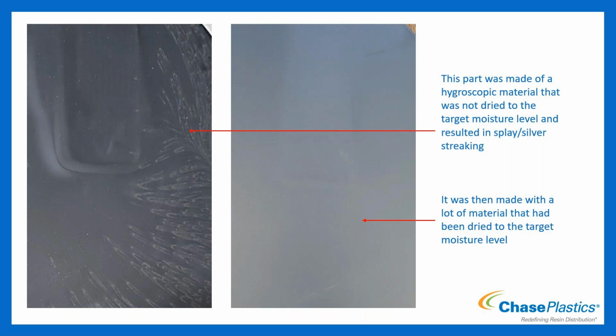That's not necessarily the case all the time with the inconsistent color mixing. It tends to be more just mottled and random in appearance when you have color mixing issues. Or you'll see the polymer separate from the colorant itself more at sharp bends in the part, so it might be lighter at areas like a 90-degree turn of the flow path and what have you. So there's a few ways to distinguish between the two. But when you get the right color and polymer combination, they can look similar at times too. So I understand some of the hesitation.